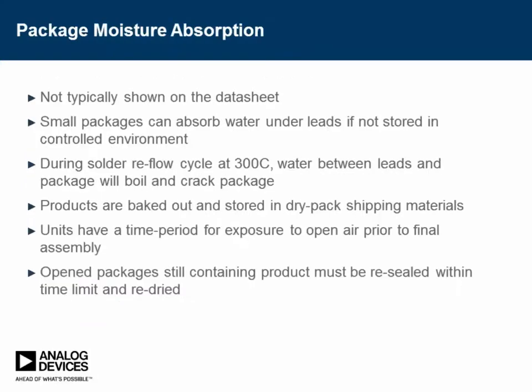So another thing that has come up, which we don't typically put on the data sheet because it can change if we change the packaging, is package moisture absorption. What happens is these very small packages, which are plastic or epoxy, have a lead frame that goes from the center of the package to connect to the chip, and then outside so you can connect to your board.